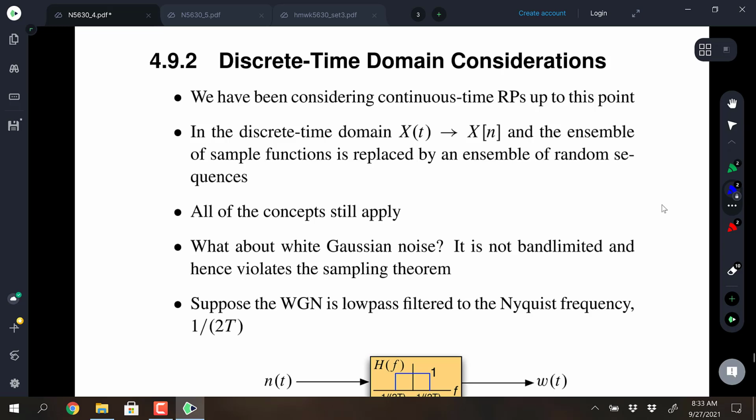Say it's 4.9 megahertz, but then because of the skirts going out, it's going to make the noise equivalent bandwidth slightly greater. It just depends. But systems are usually spec'd to within fractions of a dB of their operating point, so you don't want to come up with an analysis that's incorrect theoretically.